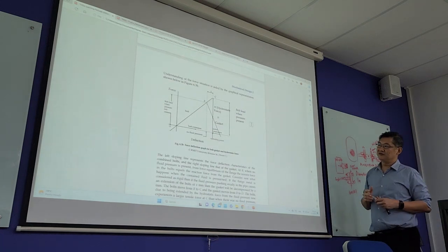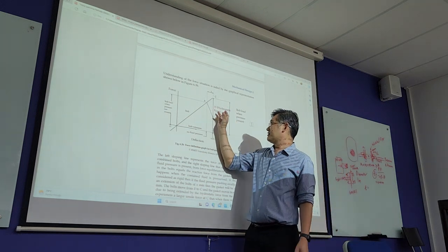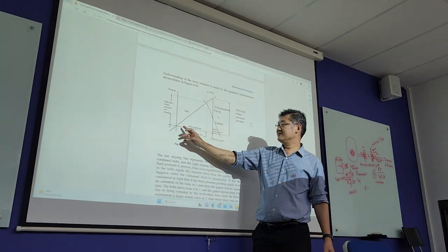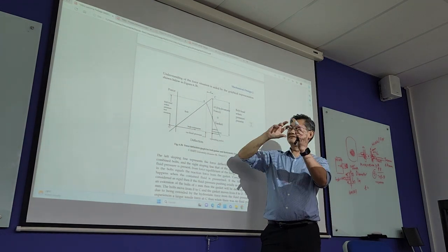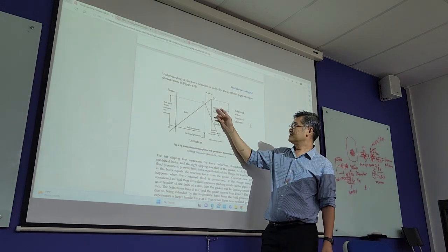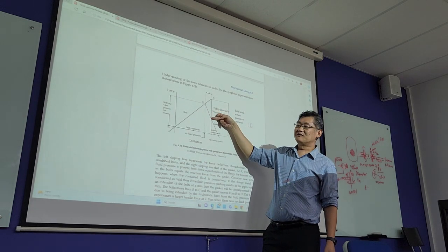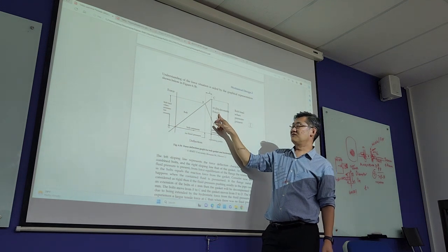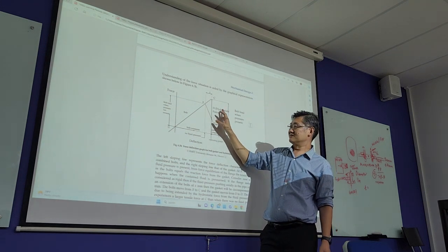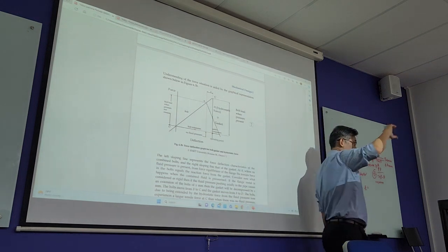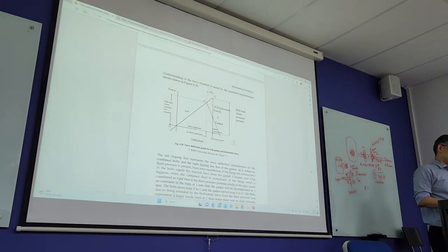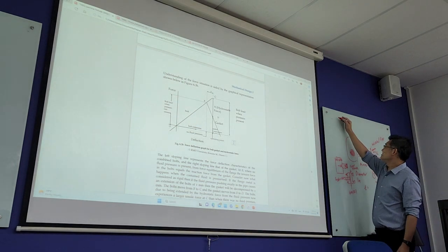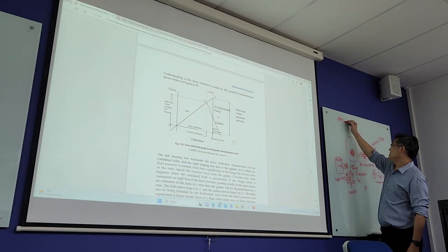And this is what happened, looking at the graph. Let's say without the pressure from the vessel itself, when you tighten the bolt, you will see the gasket compress. But when there is a hydrostatic force, you can see the gasket decompress a little bit because of the hydrostatic force from the vessel itself. So the graph actually shows you the force pattern with or without the hydrostatic force. Important is to look at operating and seating for this question.